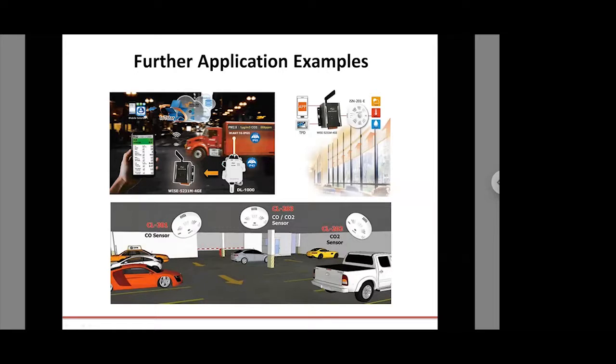At the top right is that diagram from the ISN201. A great use for the ISN201 is to program your lighting schedules based on live readings of illuminance, temperature, and humidity. You can raise and lower the shutters. You can trigger lighting cues based on the light that's coming in. So you have morning, noon, and dusk, say, different lighting schedules for a library, a restaurant, or another large building. And you can trigger those based on live readings instead of just having to do a schedule.